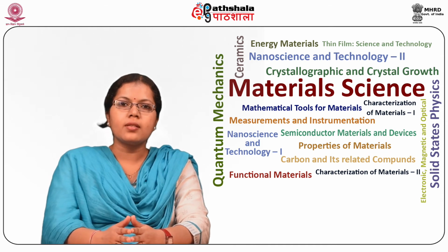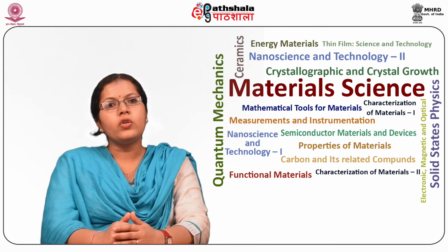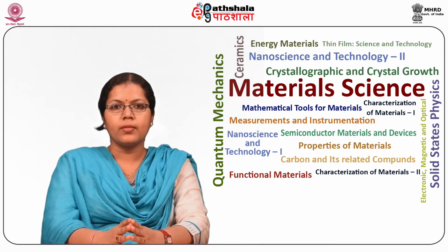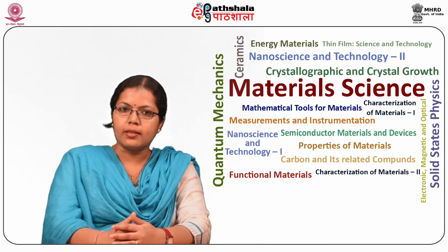Multi-range ammeters are used for ranges from 1 to 50 amperes. When using a multi-range ammeter, first use the highest current range, then decrease the current range until a good upscale reading is obtained.